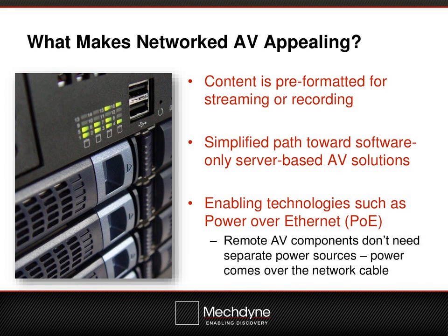We like enabling technologies such as Power over Ethernet. We love Power over Ethernet. It makes the install, again, very easy to do, because the power goes over the network cable. So you don't have to worry about having an electrician come in and add an electrical outlet where you need it to connect to that device. You just make the network connection from the Power over Ethernet enabled switch to the device that's ready to take power, and it gets its network and all its traffic from that network cable, but also its power. So it's already powered and ready to go wherever you want to install it.